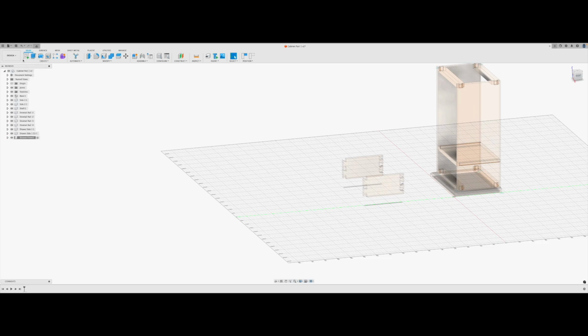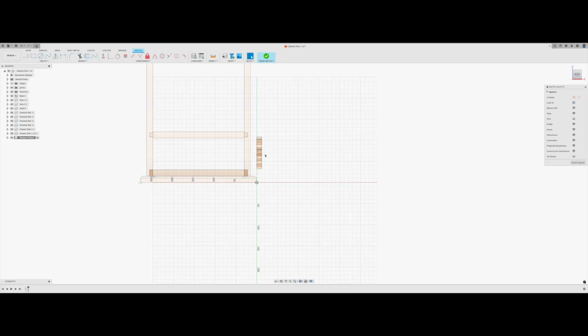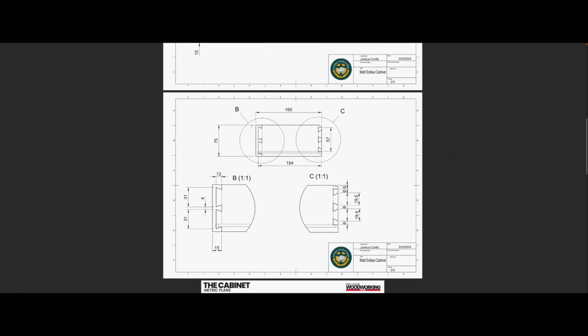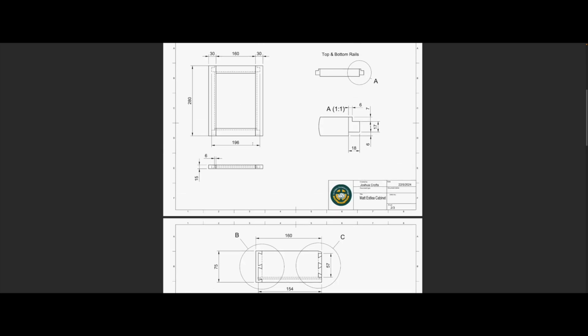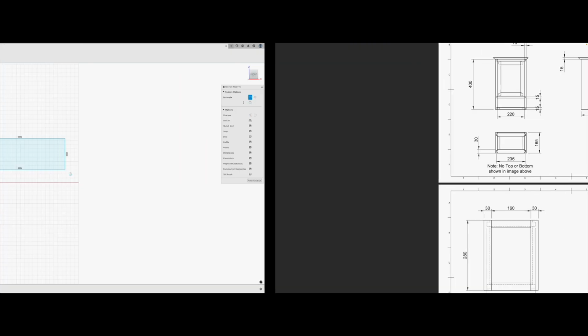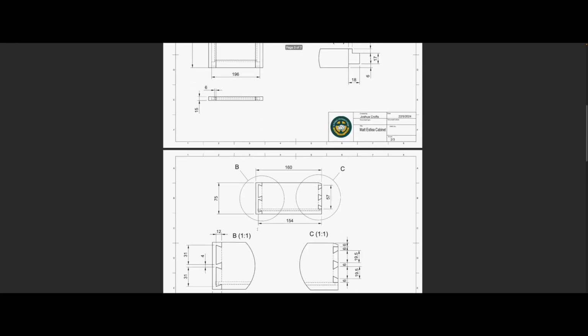So we're in our draw front, sketch on the front. If this pops up, we're just going to say revert position, which just means put them both on top of each other again, which is fine. Now, draw front is something like that. Now, how big is it? It is 15 this way and 220 this way and 75 tall, I believe.